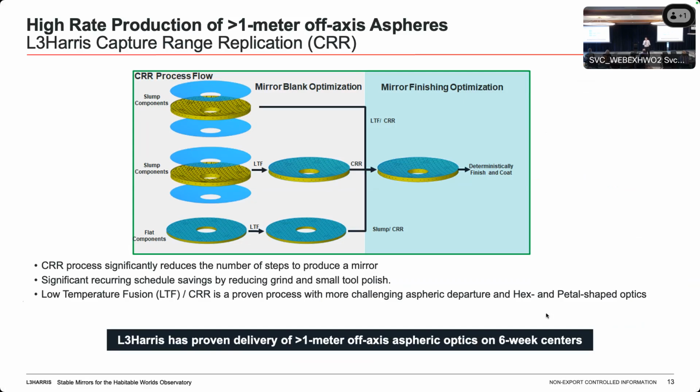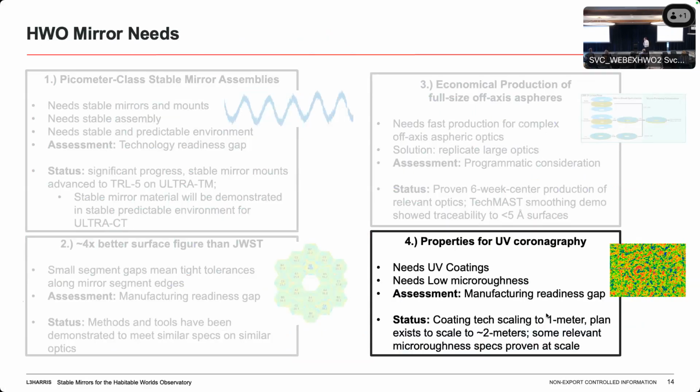And if you're creating a great many optics, you can reach a certain figure repeatedly, and you can go from there to deterministic figuring, where we measure it, we change the surface with ion figuring or magnetorheological figuring, where we take away material selectively just to get to the perfect geometric shape for Habitable Worlds. And then eventually we converge within a handful of nanometers and we meet our specification and we move to integration. We've actually demonstrated making mirrors like that 1 every 6 weeks. So we have done this at a relevant rate, at a relevant scale.